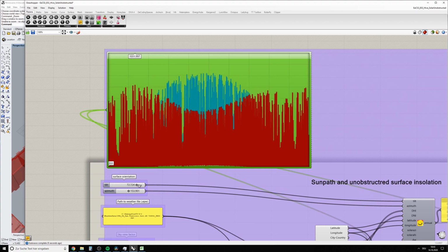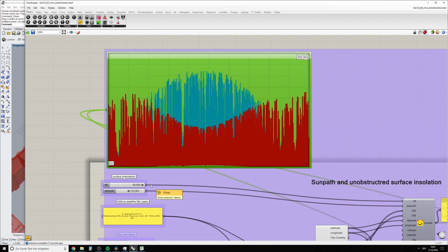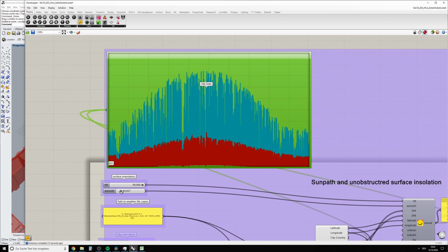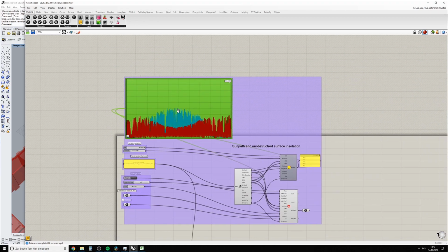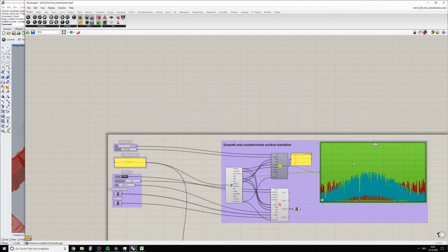And yeah, when you tilt it to, let's say, 90 degrees, which would be a normal straight wall, and then you start rotating this to north. So these values are, by the way, in degrees, and 0 would be north, so would be 360, by the way, and 180 would be south. Yeah, you can observe how your surface then performs in terms of solar irradiation. Alright, so that's this part. Let's move this back here.